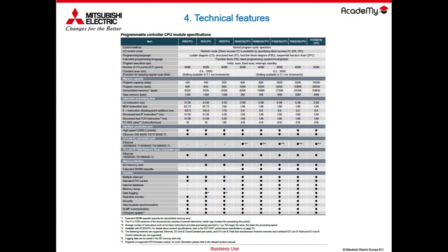It means having a CPU in a single module. So in a single case, a single device, two are actually integrated: the CPU R04 in the case of R04EN, and an additional module, which is the RJ71EN71, an information module that carries two additional Ethernet ports. On one of the two additional ports of this expansion, we can manage a master if we link the fields to 1 gigabit. So it's like we have two parallel options.